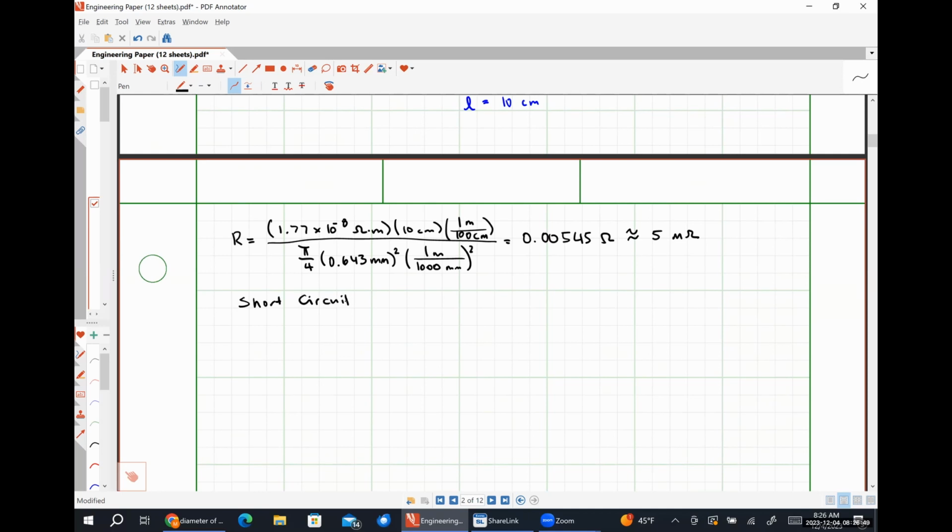So that brings me to the concept of short circuits and open circuits. A short circuit as an element is really just going to be a section of wire in some greater circuit, okay? The resistance is going to be 0. And since the resistance is 0, Ohm's law tells us that the voltage drop across this section of wire must also be 0. So anytime we have a short circuit, the voltage drop across that short will always, always, always be 0. We're going to use this in our circuit analysis very, very regularly, okay?